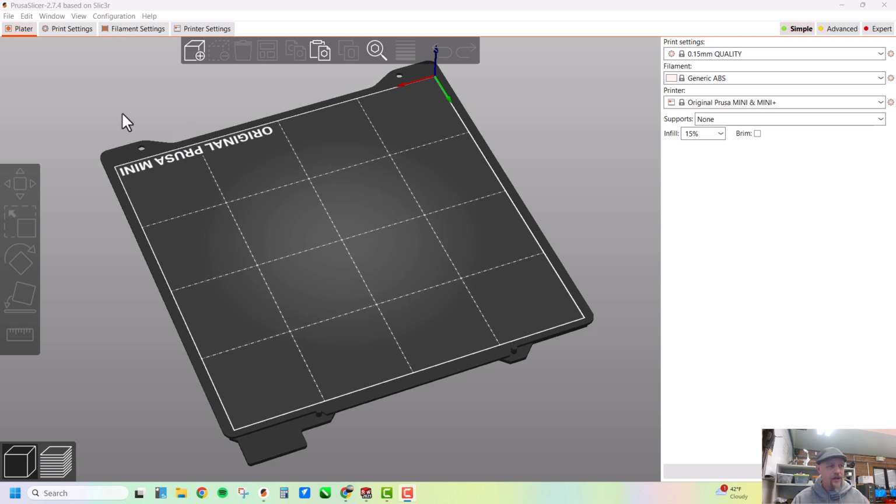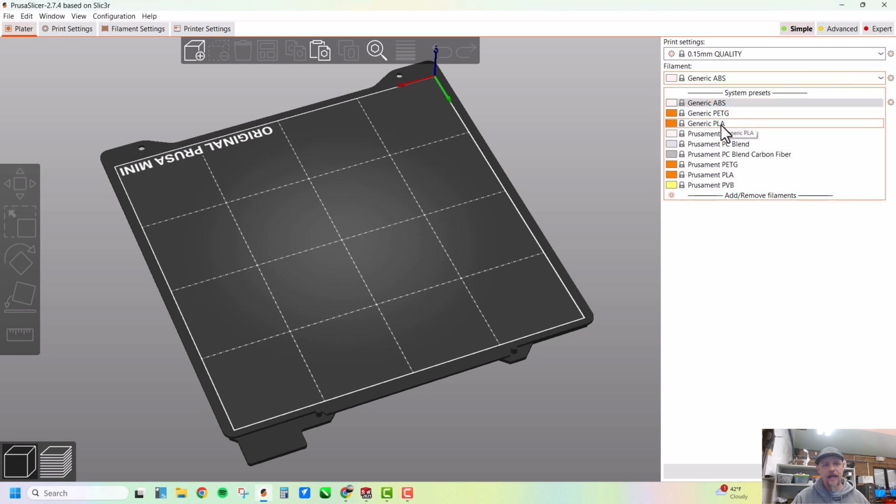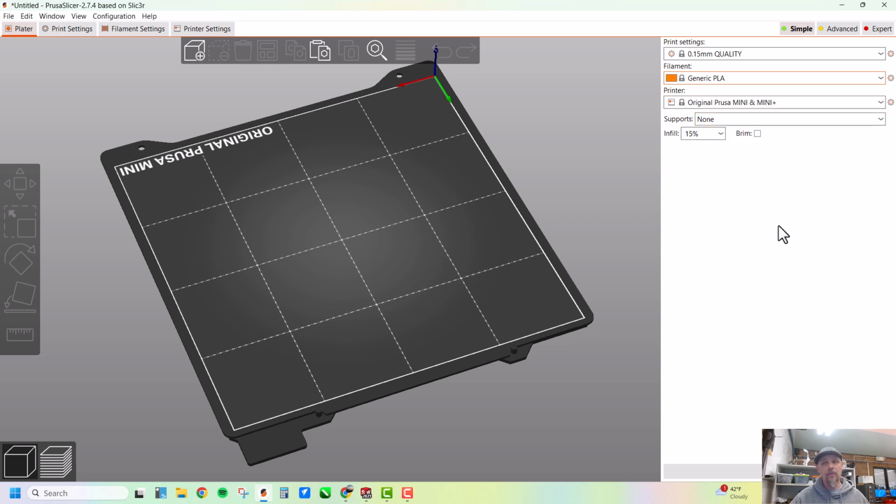We don't know how this is going to open up, but there are a couple of settings we need to do right away to make sure it's compatible with our printers here at Montlake Terrace High School. First of all, we're going to go to the material, and you're going to choose generic PLA. As you get more experience, you might decide to print in something like PETG or ASA, in which case you'll set it differently. But if you don't know what material you're using, or you're just starting out, you're going to be using PLA.